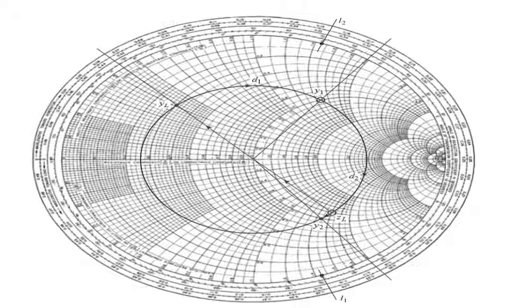So for that, we know the point Y1. Find the complex conjugate of this point. The value of this y1 has been found out as plus j 1.43. Taking the complex conjugate of this point, it becomes minus j 1.43. So minus j 1.43 comes over here, and then we draw a straight line passing through the center outside, and this line becomes L1.